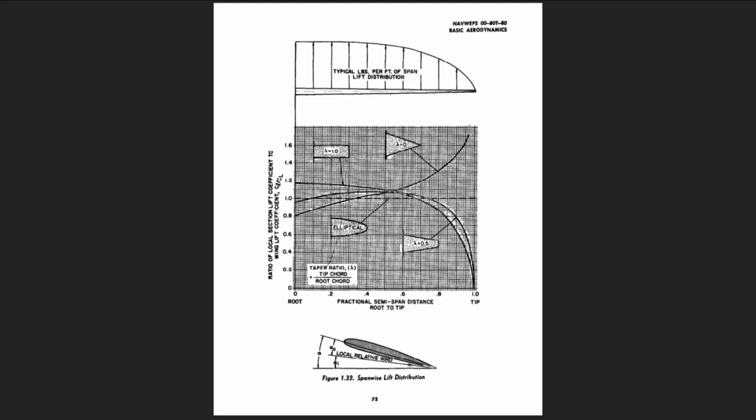At the other extreme of taper is the pointed wing, which has a taper ratio of 0. The extremely small parcel of area at the pointed tip is not capable of holding the main tip vortex at the tip, and a drastic change in downwash distribution results. The pointed wing has greatest downwash at the root, and this downwash decreases toward the tip. In the immediate vicinity of the pointed tip, an upwash is encountered, which indicates that negative induced angles of attack exist in this area. The resulting variation of local lift coefficient shows low c_l at the root and very high c_l at the tip.